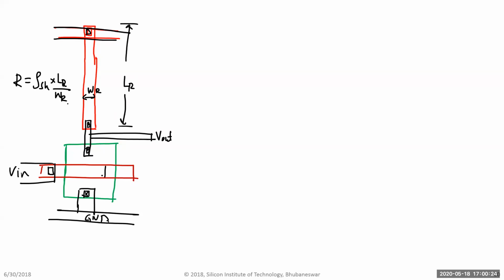And this one is the length of the transistor, and this is your W. So they're two separate devices, but obviously they have a similar response. You increase the length for the resistor, your resistance will vary. You never increase the MOS length, because you want the MOS to be as small as possible.